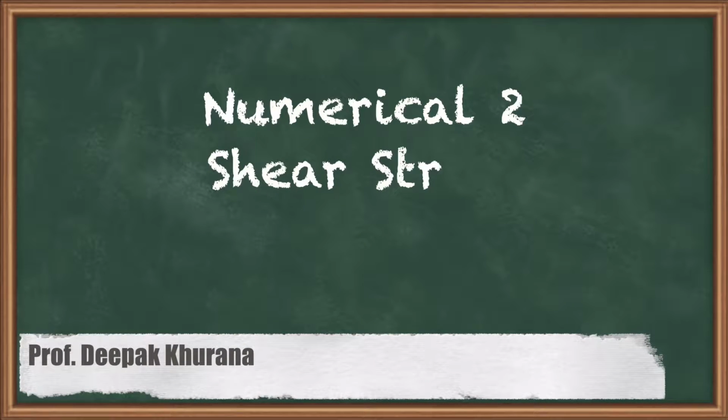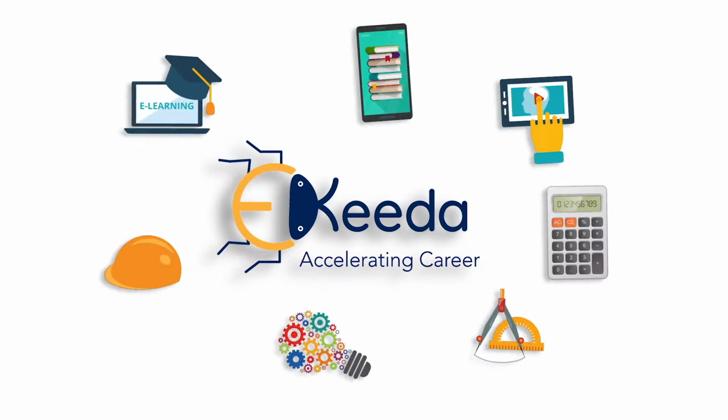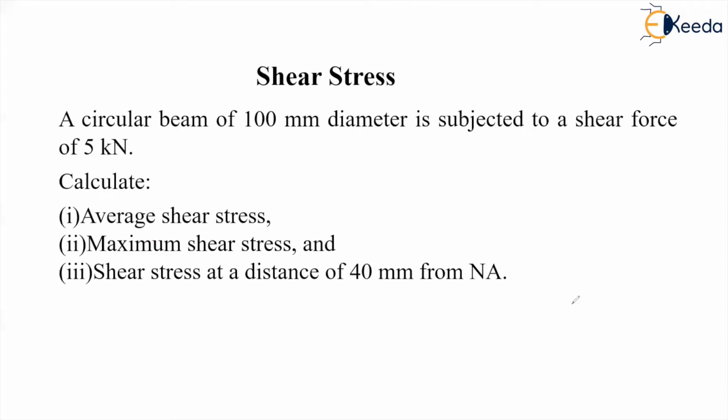Hello dear students, in this session we are going to solve a numerical on shear stress at different sections. In this question we are given a circular beam of 100 mm diameter that is subjected to a shear force of 5 kN. We have to calculate the average shear stress, maximum shear stress and shear stress at a distance of 40 mm from the neutral axis.